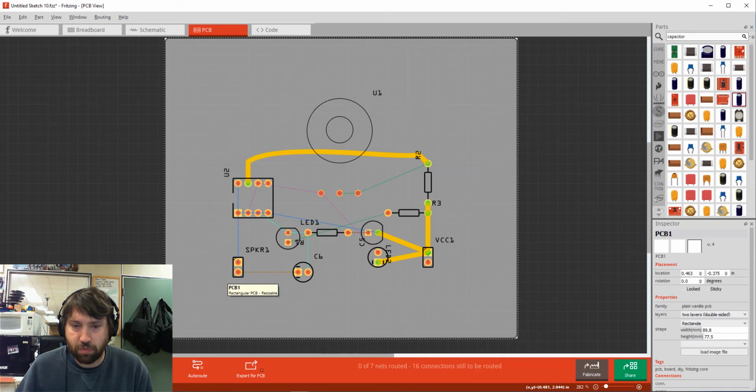Now, if you look at the bottom, down right about here, it will tell you the current X and Y position. So if I look at my leftmost through-hole component, this says X is equal to 1.1 inches. If I move to the left, it's getting smaller and smaller and smaller. So I want the outside of my shape to be at about 0.1. Right?